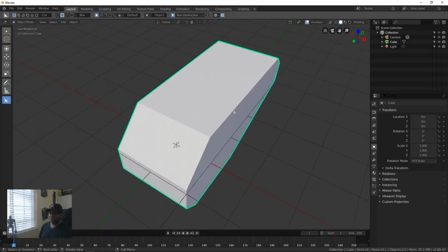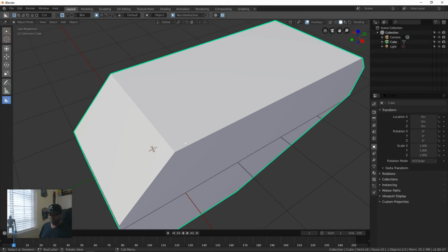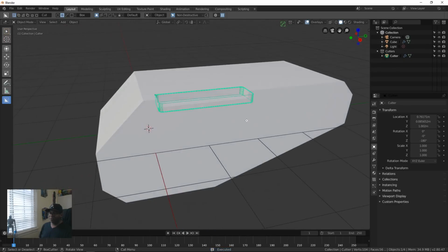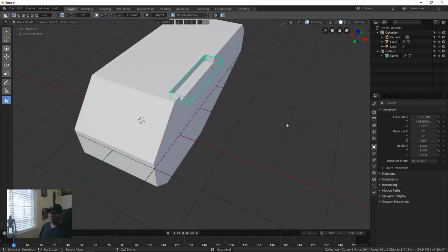There we go. And so now let's just take the shape. I'm going to hold Control again, pull out a box, put it in, do a bevel, right? And these edges will basically be the edges that will be in our geometry at the end. So I'm just going to take this, hold it, click once. It's still active, but now I'm going to go from Control to holding Shift and just clicking it. And this will leave a live box for me to have.